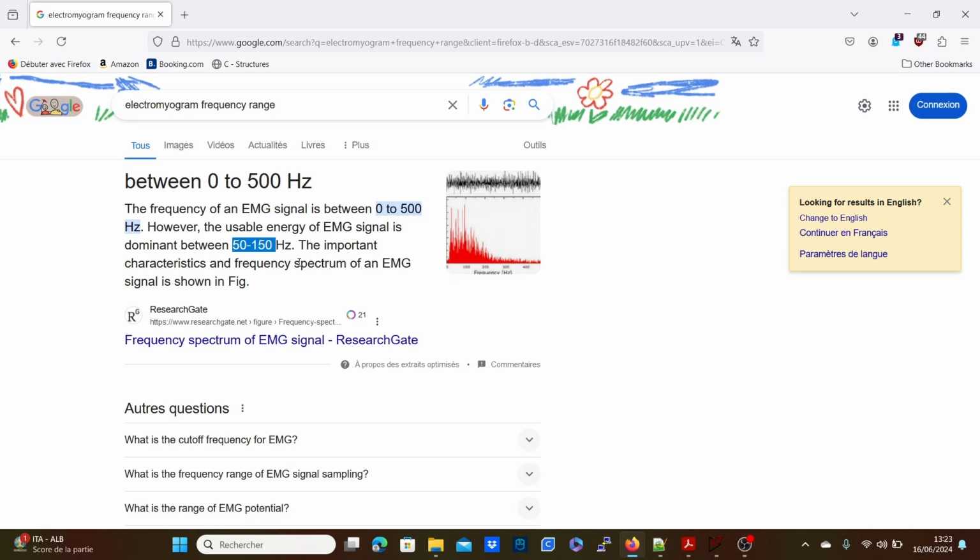And yeah, as I said, what will make the difference between one signal and another is going to be filtering. Now, it's true that you have, for an EEG, for example, signals that are just crossing or superposed to each other, especially with the EEG, which is really, really difficult to process. Hardware filtering for an EEG is not enough. You need to also include a lot of digital signal processing through digital filters.